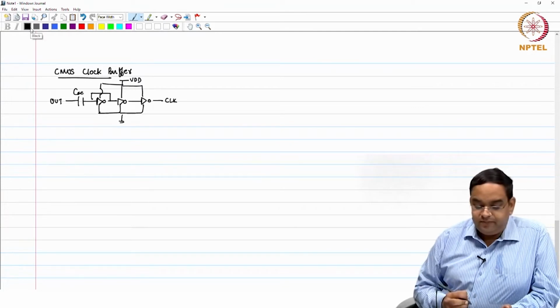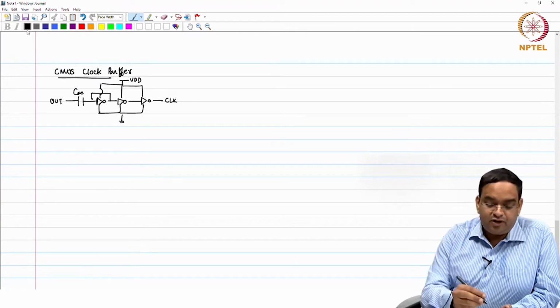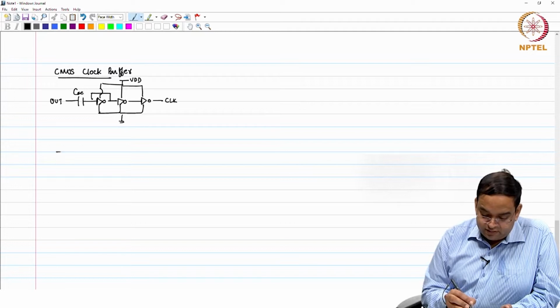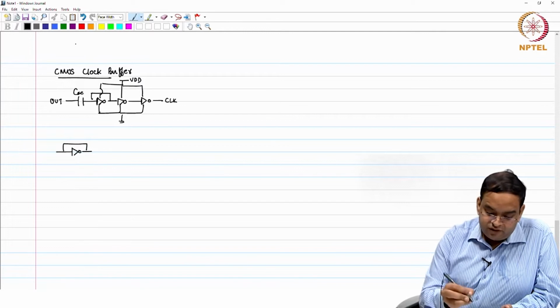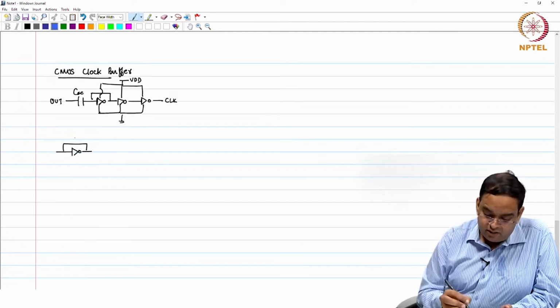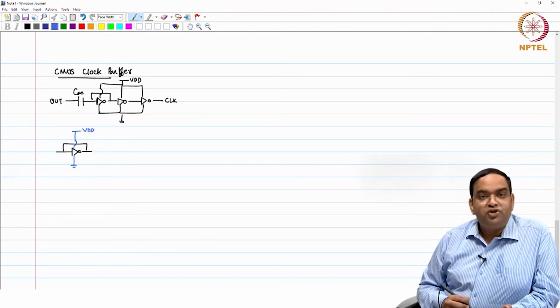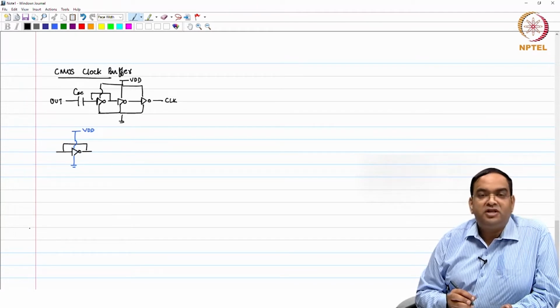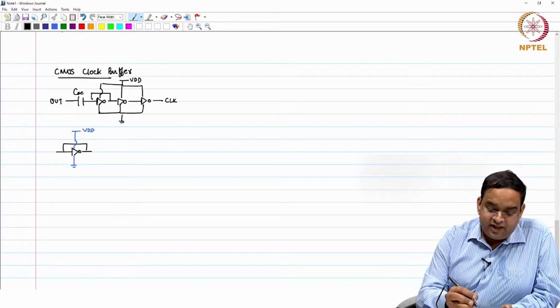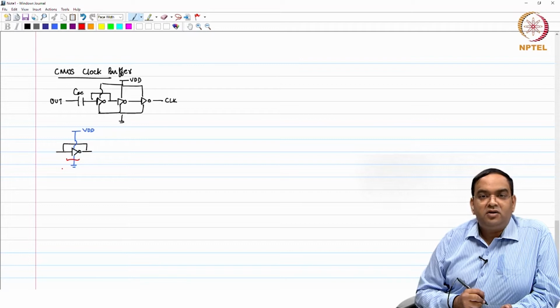So, now if you think about it, you will get the desired clock. The buffers will add some amount of noise. Now, when you are doing a power optimized design, this inverter which you are seeing here is always conducting current, because your gate and drain are shorted. So, both PMOS and NMOS are always conducting. So, sometimes this inverter has a lot of power or current consumption.